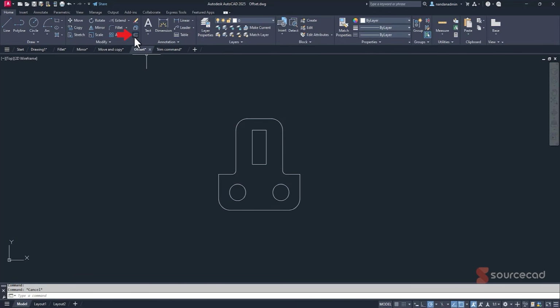Now I'll go to offset and let's specify an offset distance. So this length, let's just check it, and you can actually check it simply by hovering your cursor and then moving it along. And if you move it on this tooltip, you can see the distance changing. So I can now see that this distance is about 1.6 units. So this entire length will give me an idea of the scale on which I'm working.